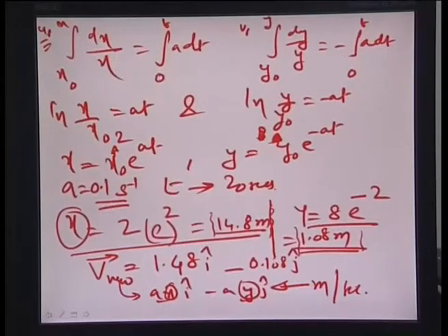Also we would like to determine the path line equation for this particular example, and for that we also need to find out first the parametric equations, that means the relationship between x and t and y and t, as we had done in the earlier example, and then try to solve for time. And from there we can find out what the path lines are really.